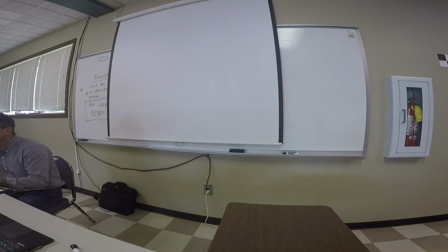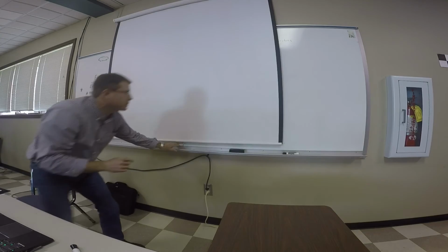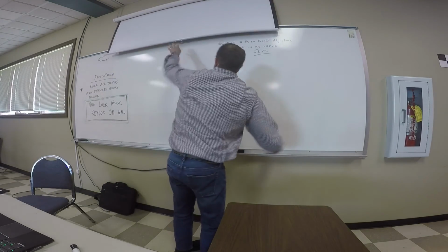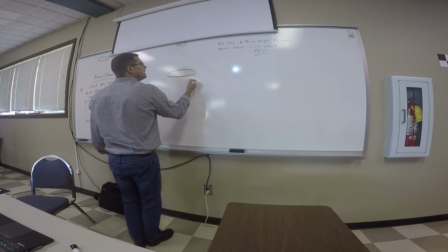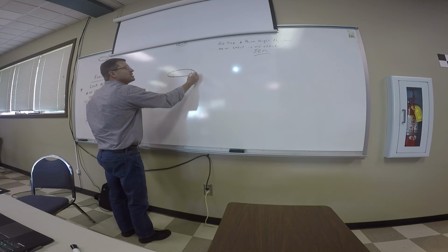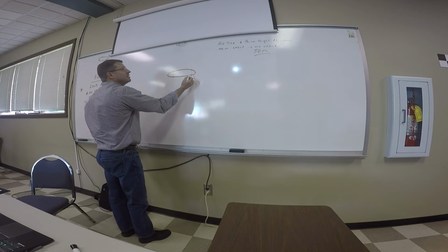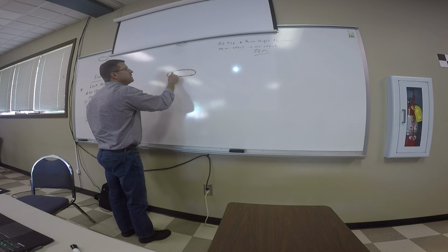So typically we're doing PC to PT, but correct me if I'm wrong, I believe you can just go PC to PT and not shoot the POC, and it will draw the curve. If it's a good, consistent radius, and you're shooting an island, and it's tangent. So if we're shooting a bunch of islands out in a parking lot, we don't necessarily have to have that point right there. You can draw that around, and tangent's going to run back down PC and PT.